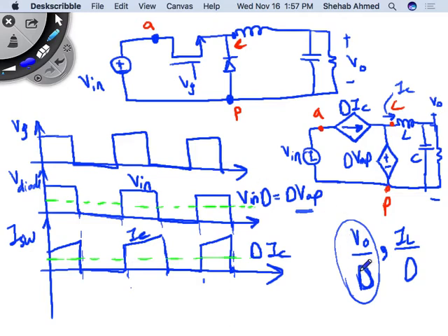Okay. But can I just double check? Do you see the relationship now between this course and 420, right? And it depends on the idea of voltage regulation. Because we have voltage regulation, I have to change duty cycle. How do I change duty cycle? I change duty cycle by coming up with a transfer function. This transfer function, you will put a value of L and C, and you will see that if you increase the value of C, you will see that the dynamic response is a lot slower.